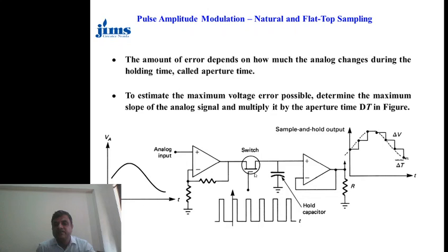Again this particular switch is turned on and this circuit is connected to the input, then charging is performed again. Similarly, at this point of time, the switch is off, and when it is off, this capacitor does not get a reverse path to discharge. It means this particular voltage is again maintained at this level. Again at this point, the switch is on, then it is charged again. It means a discharge path is not available for this capacitor.